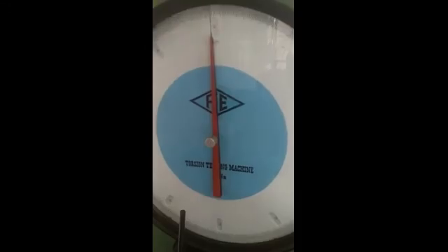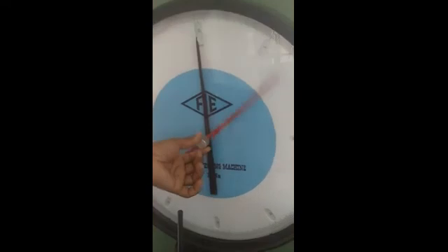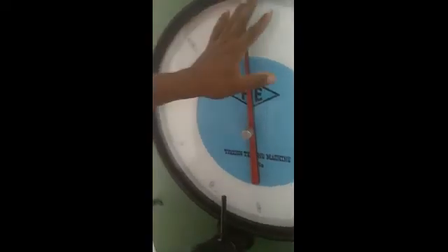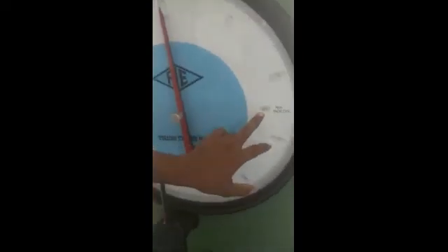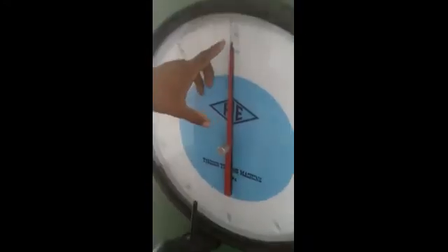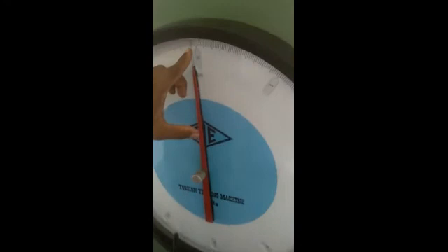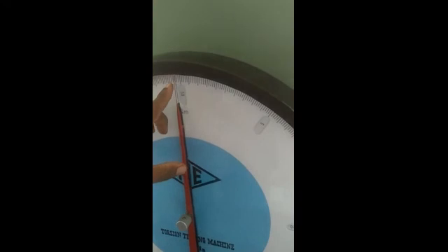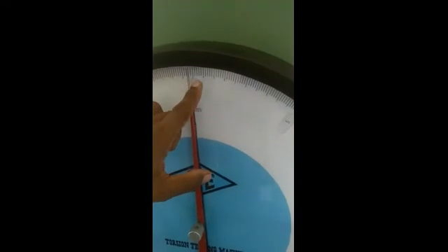If we see the scale, we can see one needle that we have to set manually at the start. From here we can see the scale with a least count of 0.1 Newton meter. So least count is 0.1, that means 1 division is equal to 0.1. So 0.1, 0.2, 0.3, 0.4, 0.5. From one big line to the second big line it is 0.5. So here it comes 1, 2, 3, 4, then 5. So the reading goes like this.